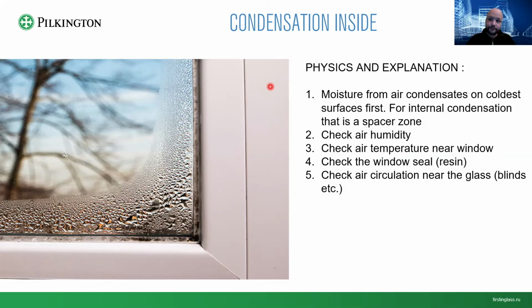For example, if your window is usually closed by the blinds or curtains, that means that hot air from the room cannot get to the window, cannot get to the glass. And as soon as you open the curtains, all of the water will be condensated on the inner surface of your window, or of your IG unit, of course, also.